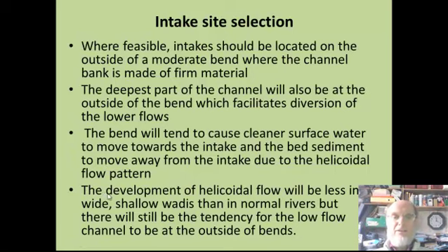However, helicoidal flow is going to be less well developed in wide, shallow wadis than in normal rivers. There will still be the tendency for low flow channels to be at the outside of bends.